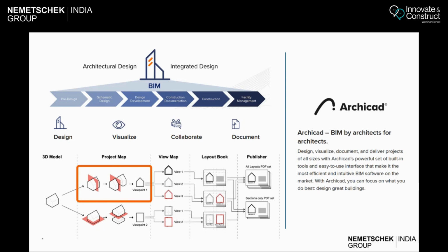interactive documentation style. So basically, the concept is that we create an information-rich 3D model, and from the 3D model, we create horizontal and vertical section cuts, which are our viewpoints, and viewpoints are nothing but our plans and sections. So from the viewpoints, we create multiple other views that will be on our view map. So these are the different views that I create.